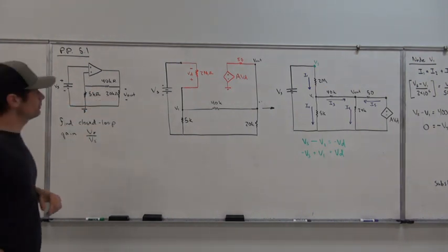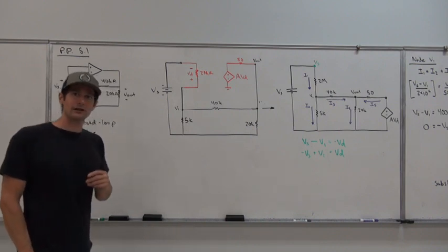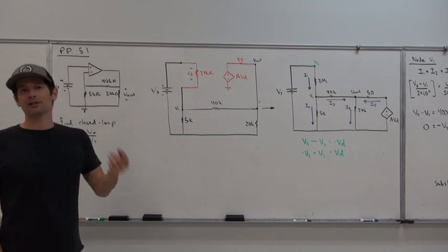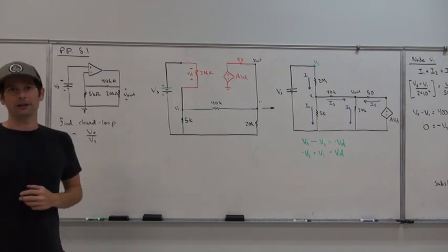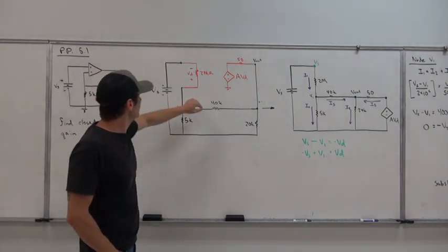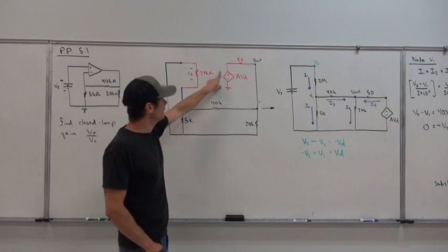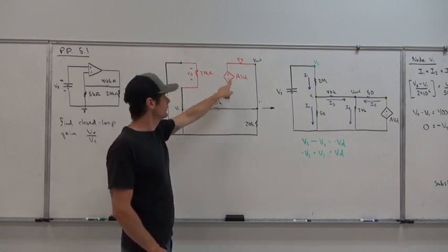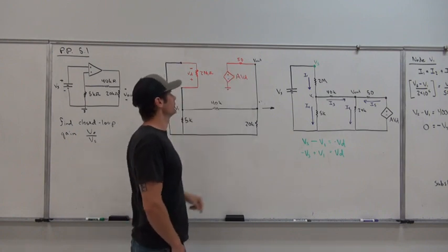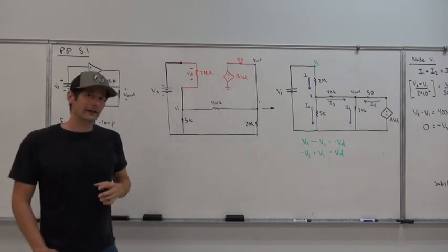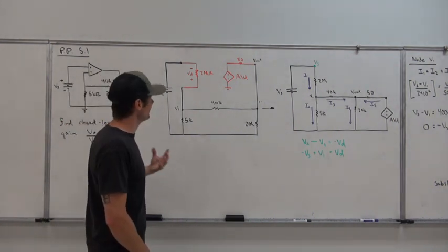So what we're going to do is replace the operational amplifier with its equivalent model and once again solve everything with nodal analysis. Then we're going to resolve the problem under conditions derived from looking at the non-ideal amplifier and then utilizing the ideal op amp. If we replace the operational amplifier, we have its internal resistance, 2 mega ohms, very, very high, in which Vd is negative to positive. On the right-hand side, connected to ground, is our dependent source of the open loop gain times Vd, connected to 50 ohms. Everything in red is essentially that non-ideal operational amplifier model.